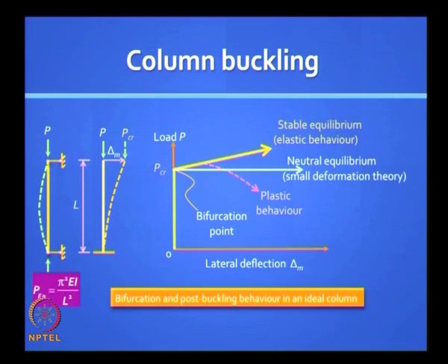You are familiar with this, right? Look at that equation. EI is in the numerator, which means if you had a member with a large flexural rigidity, the buckling load will be much higher. And in the denominator, L is coming into the picture. So if the member is long, then its buckling load is going to be much less. These are intuitively obvious, and you can prove for a cantilever it's 1/4 this value. For a cantilever, it is obviously less stiff than a simply supported case, so the buckling load turns out to be 1/4.